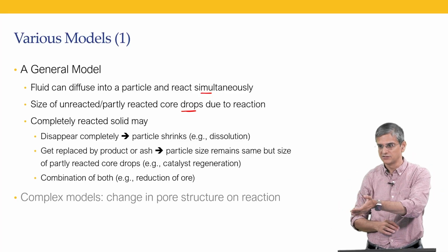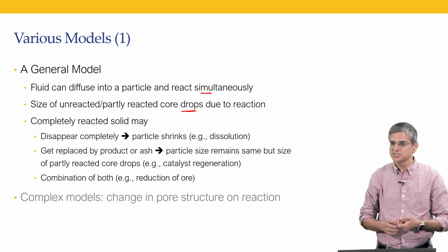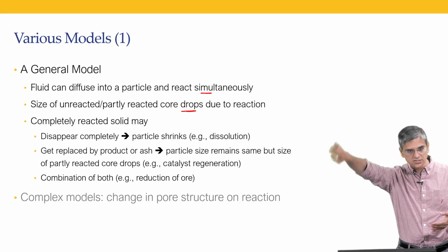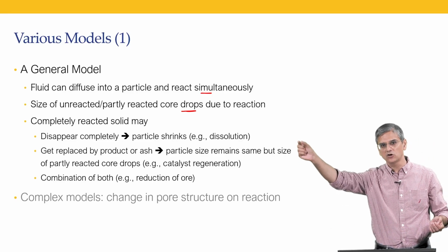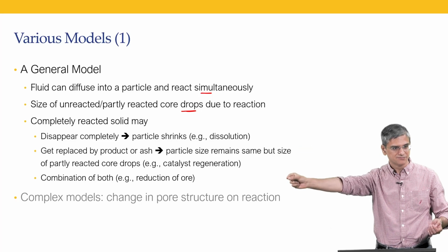And a very quick snapshot of that you already saw with a 1 mm pellet, 5 mm pellet, 50 mm pellet, right. When you plotted against zeta, one looked flat, one looked like this, one looked like that, but if you were to plot against R, your concentration will change only in this small region for a 1 mm pellet,